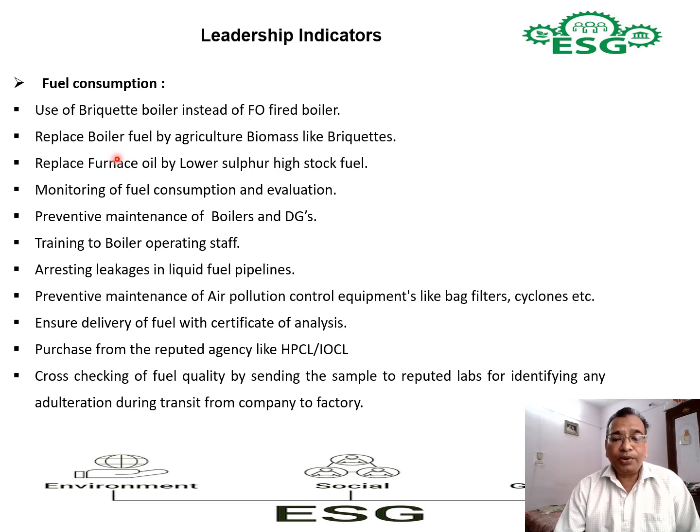Then you can replace boiler fuel with agriculture biomass like briquettes, which I have already said. So you can replace the boiler fuel through biomass, that is briquettes. Then you can replace furnace oil by low sulfur high stock fuel. This is also to reduce the sulfur emission; you have to switch from FO to low sulfur high stock.